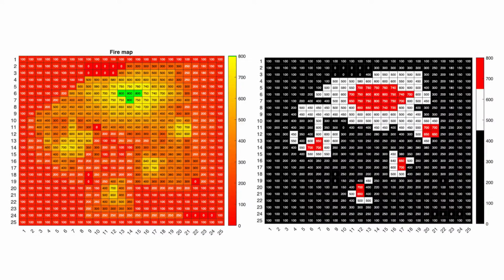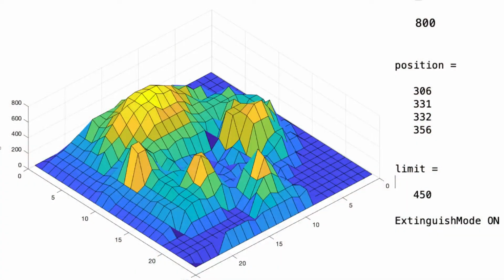And secondly, I simulated the software detection of fires with two different methodologies. The first one was with the use of a user-generated heat map as input on MATLAB, and that was to collect information like value and position of maximum temperature, as well as the distinction of temperature ranges in the image, and that allowed me to ultimately activate the extinguishing system if a threshold temperature was exceeded.